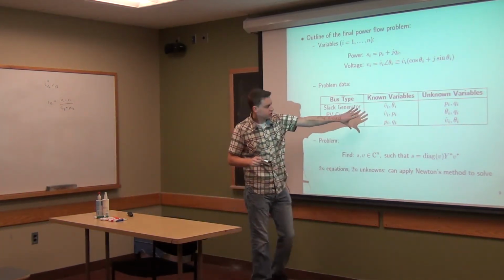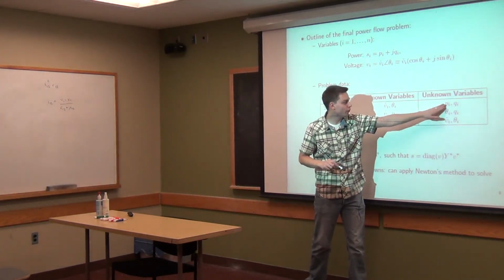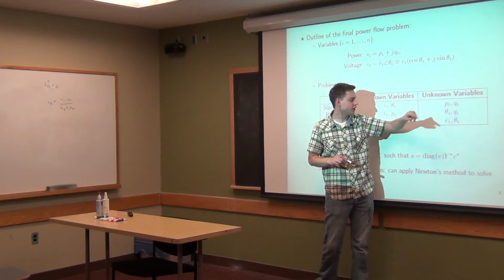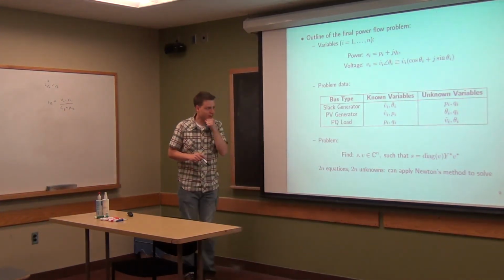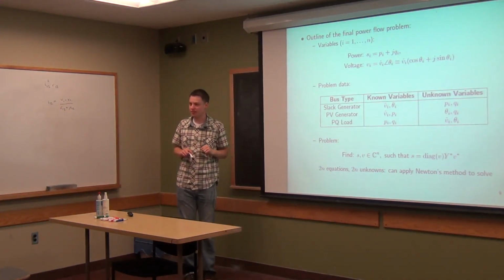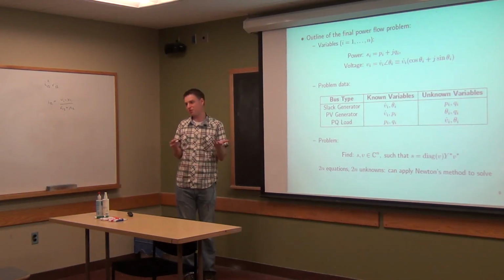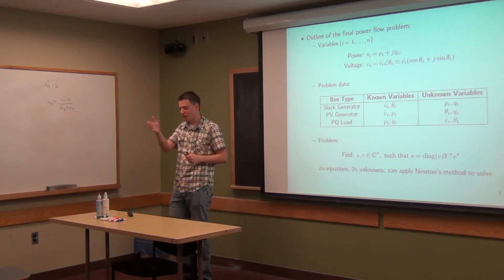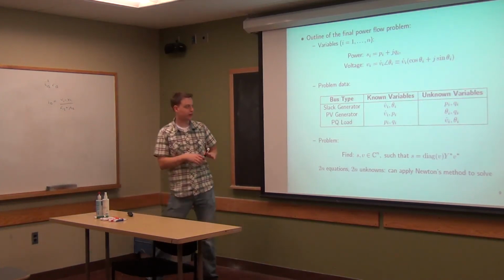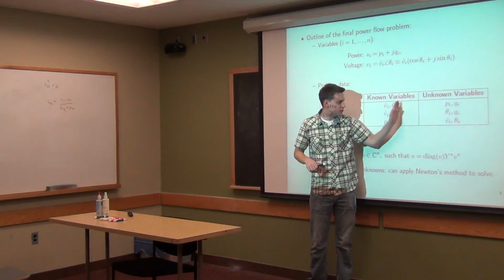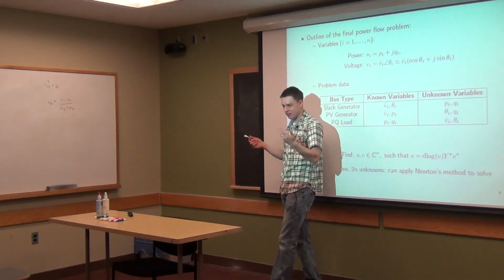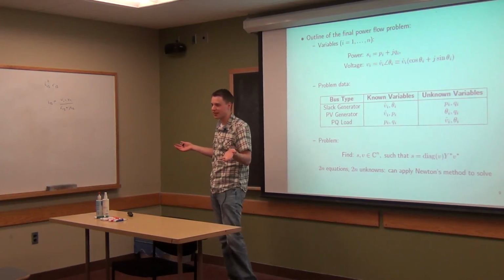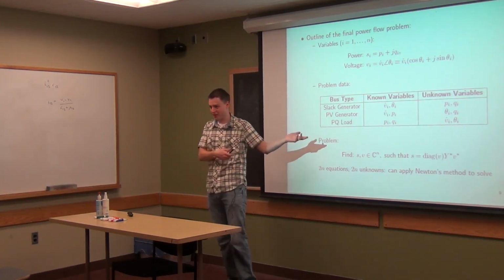And what that really boils down to is, if we don't do this, if we said let's assume power is known here and the voltage and the phase angle are known here, well, there actually oftentimes would not be a solution to that equation. There would just be no solution. This is what can happen with nonlinear equations. It just makes sense too, because if your powers here don't add up to the total power being consumed by both the loads and the network, of course there will be no solution to this equation. There's no system that can actually create that.